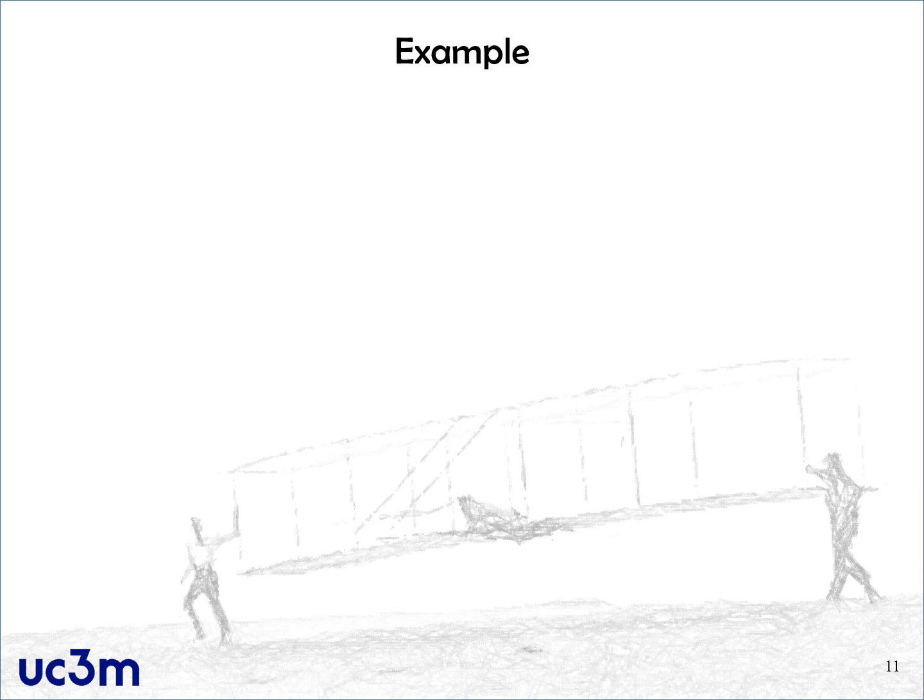Okay, so we have just found the value of the angular velocity. The next thing that we want to do is to check whether in this instant of time there is any slip velocity or not. Okay, that will allow us to determine whether this is a pure rotation, because we know that already there is some rotation, we have some omega different from 0, or if we are in the general case where we have some rotation and some slip in the parallel direction. So let us find out this parallel velocity.